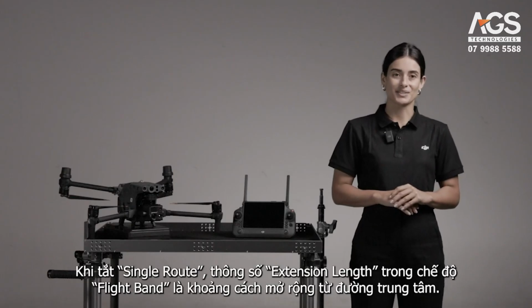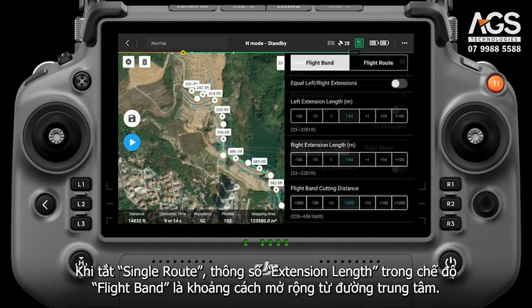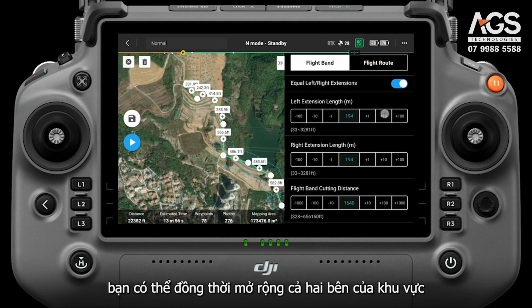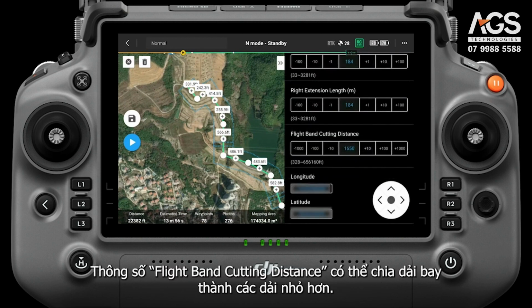When the single route is turned off, the extension length under flight band mode is the distance expanding from the center line. It is used to monitor the coverage of the target area. According to the actual condition of the target area, you can expand both sides of the area at the same time, or change them separately. Flight band cutting distance can divide the flight band into smaller parts.